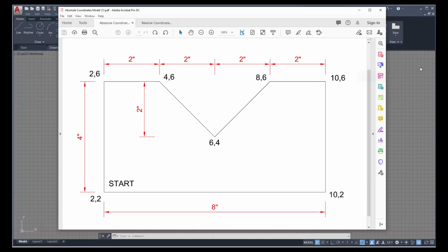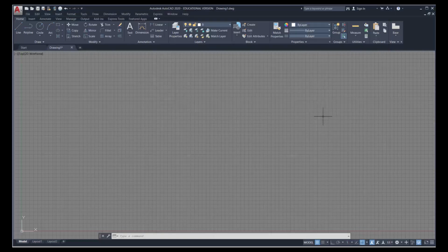I'm just going to click on the background. That will bring my CAD drawing up. And in order to initiate that page area that we're going to draw, we simply type in the word limits. So LIMITS. Now again, if you have some template files, this is already placed inside of that particular template, so you don't have to go through it. But it's worthwhile understanding what it is that we're doing in order to understand later on in the print menu what it's asking. So limits, I press enter.